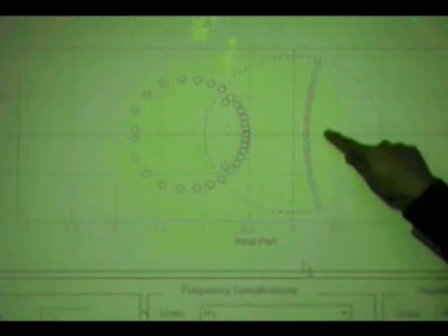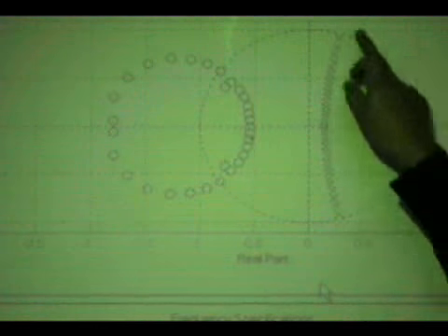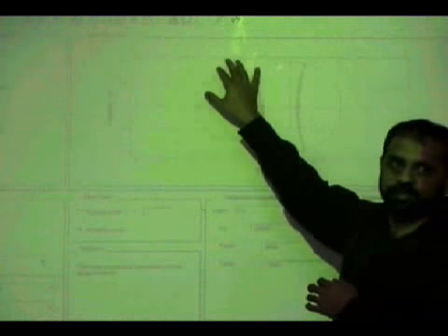If you look at the poles, they are in complex conjugate pairs. A pole here will guarantee a pole here, a pole here, a pole here. Okay, so they may be anywhere, but they have got to be inside the unit circle. So these are zeros. At this point, let's not worry about zeros, but the zeros are there, they are significant. But our worry is you can find several zeros outside the unit circle. They are not going to disturb the stability of a system, so you don't mind.